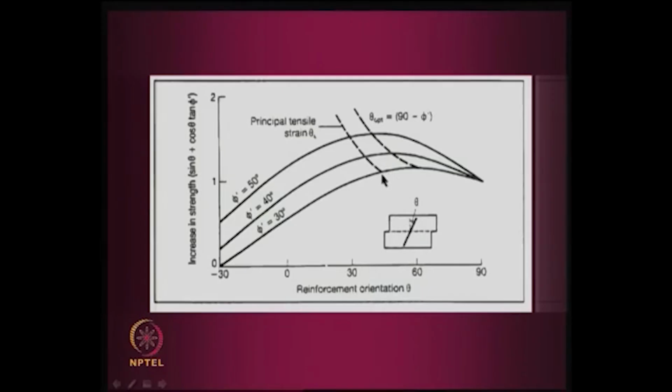So, this is precisely the reason that this technique has been very useful in geotechnical construction, whether it is for the improvement of slope stability by nailing, reinforced soil, or improvement of bearing capacity and all that. In simple terms, yes, it is very useful. And for example, between about 40 degrees to about 60 degrees, you have a failure surface, and if you put a reinforcement, the angle is roughly in the same range. So, that is an advantage.